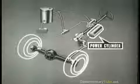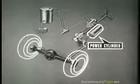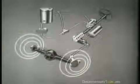The power cylinder converts hydraulic pressure into mechanical force, which in turn actuates the pitman arm shaft and lever and the pitman arm, turning the front wheels of the vehicle through the steering linkage.